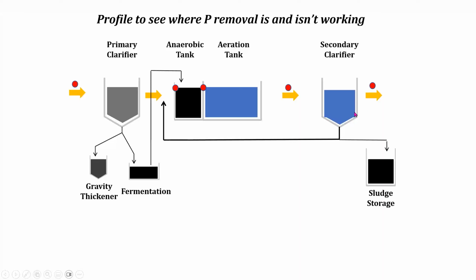If it's possible, let's lower that sludge blanket. Nick talked about adding chemicals in distribution boxes because of the turbulence. There's also often dead spots in some distribution boxes. If there's dead spots, solids are going to accumulate there, and any solids that accumulate in dead spots downstream of the aeration tank have the potential of releasing phosphorus, which will then flow all the way into the receiving water.